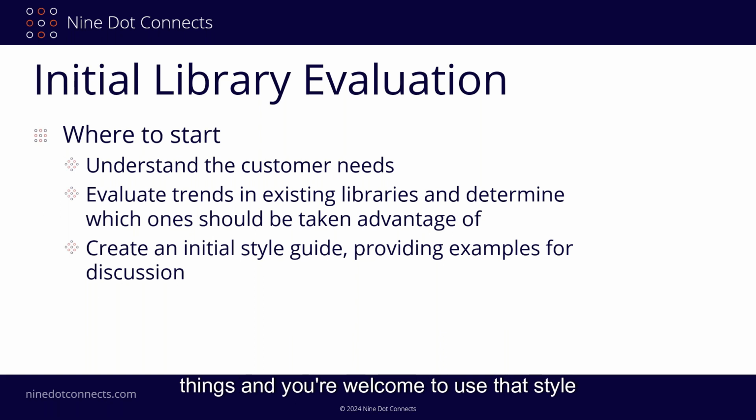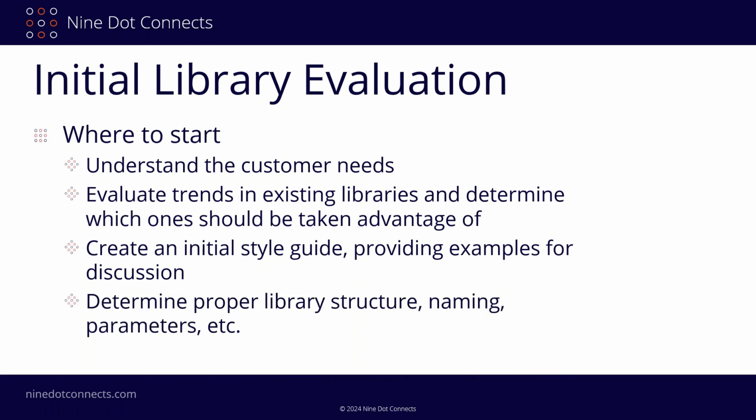And you're welcome to use that style guide for your own pleasure and be able to share it with other people within your organization, if you ever plan on making changes to your library. And then we determine the proper library structure, naming, parameters. It sounds like that's the last thing and the least important, but it's really not. The library structure, we're going to talk a little bit about that. Naming, we're going to actually have a webinar series on naming components and symbols and things like that. And parameters are a big deal too, and I'll talk a little bit about that today, but not much because we're mostly talking about symbols and footprints.